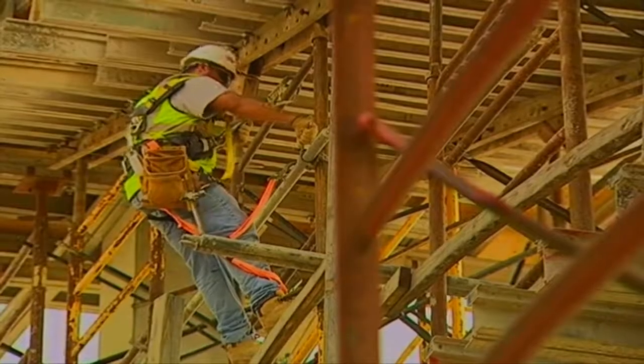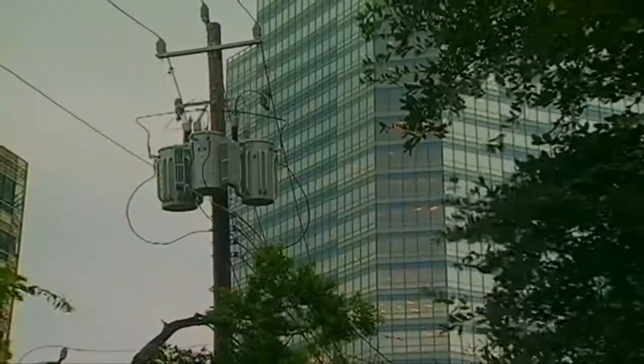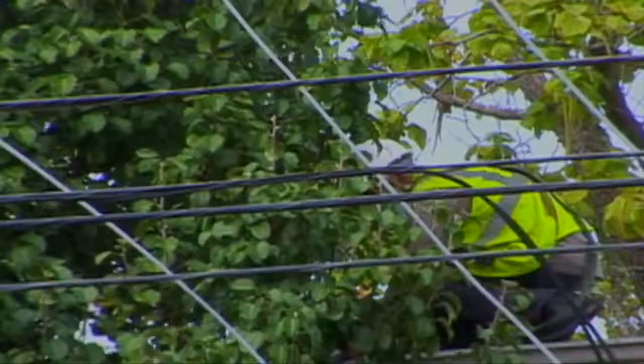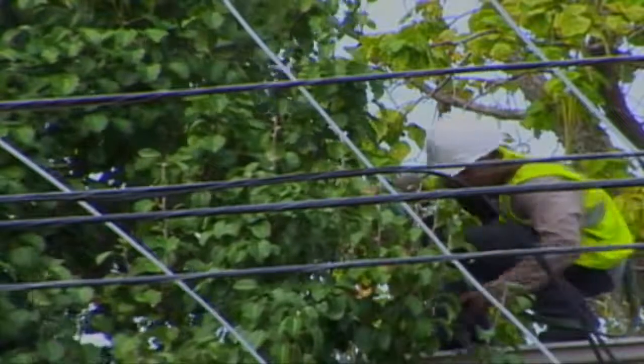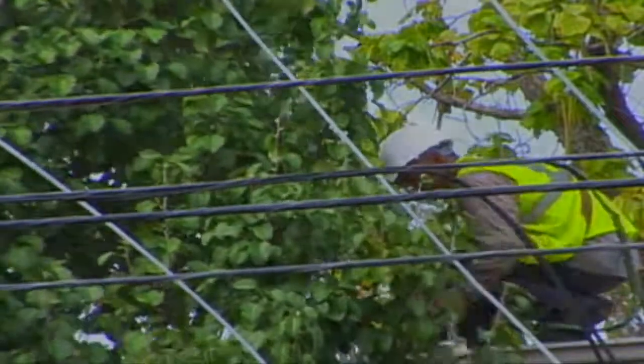Never access a platform by climbing cross bracing. Electrocution, mainly caused by scaffold being placed too close to energized overhead lines. Remember to place scaffolds at least 10 feet away from the electric line depending on the line's voltage.